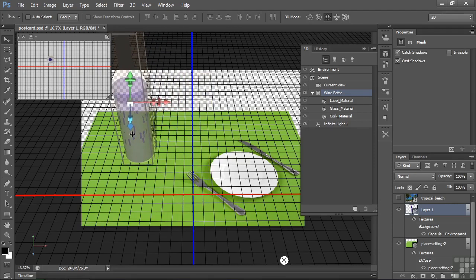And I want to scale it down a bit too. So I'm going to hover over the scale uniformly thing and pull that back a little bit. When I do this though, it lifts it up above the ground plane. One of the little anomalies of scale is that it scales at the widget, not at the bottom. You can see we're above the ground plane by looking at the secondary view here.